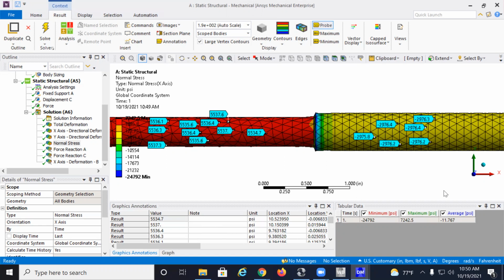The finer mesh has reduced the percent error. Can we always afford to go that fine when we have bigger parts? Not really. But this is just to demonstrate that you want to make sure you use a reasonable size mesh such that you're not compromising the solution. With this, we were able to answer all what we were asked to find.